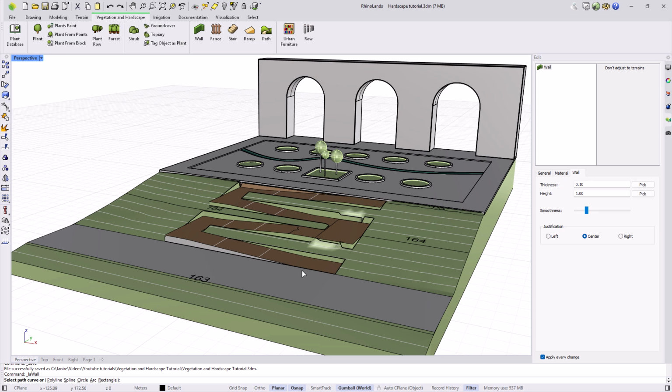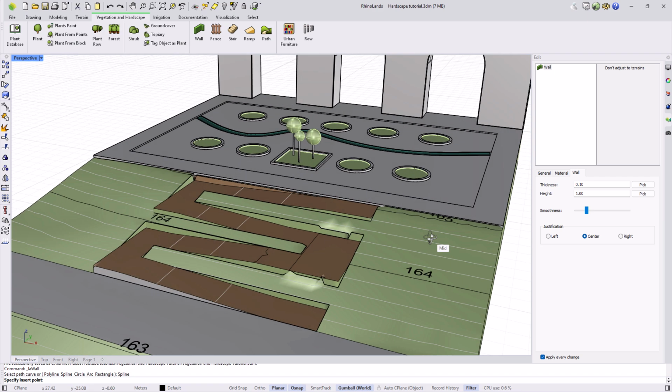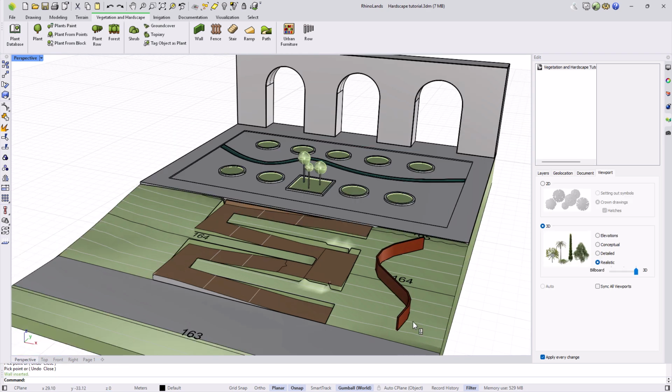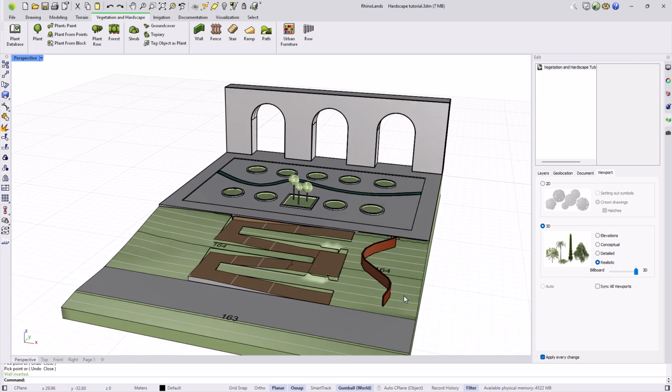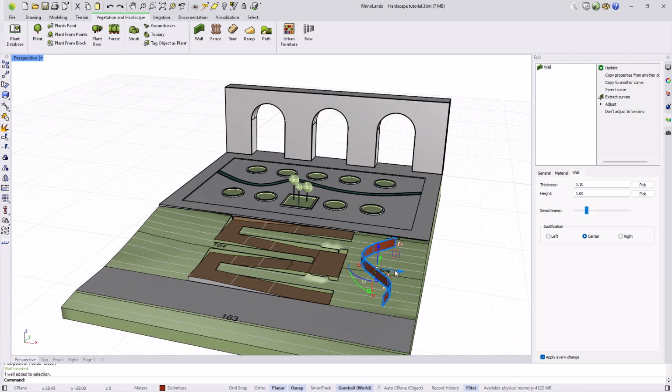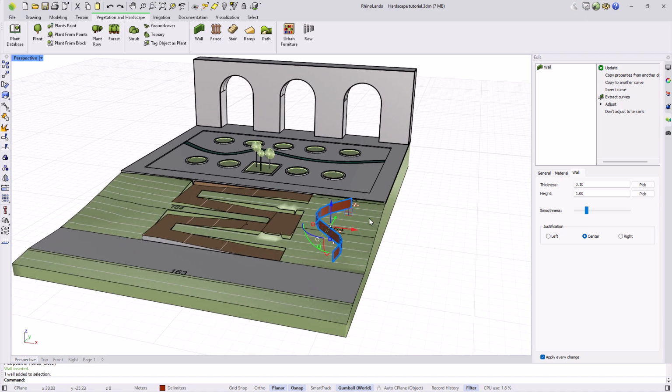Once its parameters are accepted, we can select an already created line in the drawing or create one using the options in the command bar, as well as through a curve. We indicate points in the view to generate the wall along this path. As you can see, the walls and other elements we will see automatically adjust to the surface of the terrain, as long as there is terrain at this same elevation. If I move it outside the terrain, it will respect the position of the curve.